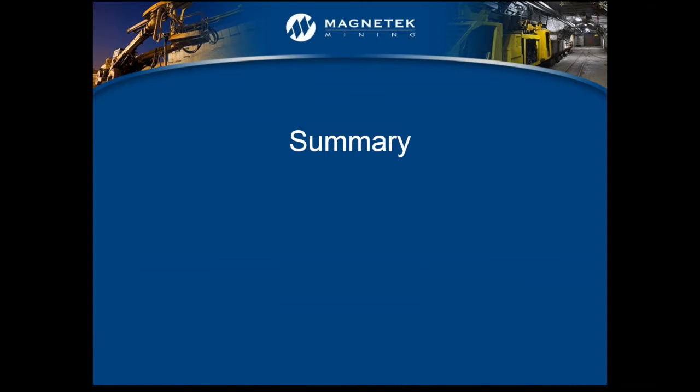So in summary, we talked about varieties of types of motors typically seen in underground mines, AC and DC in particular. We also reviewed electrical and mechanical speed control methods, efficiencies that one would see with those, and we came to the conclusion that AC PWM drives are really the most common and most efficient of the varieties of opportunities we have there. We looked at a variety of applications, in particular an HVAC fan application, comparing outlet damping to varying the speed.